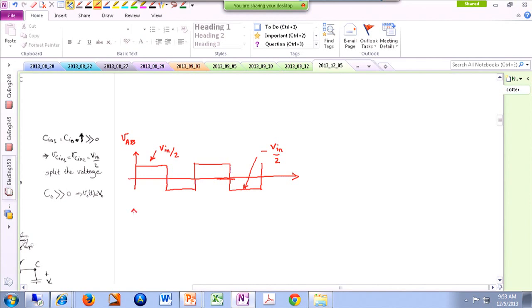VCD is almost the same thing with a little bit of a phase shift. And there is a reason that we have a phase shift, because if you analyze an LRC circuit over here, the current of the inductor is shifted from the voltage of the input. It actually lags a little bit. All right. So now this phase shift is this much.